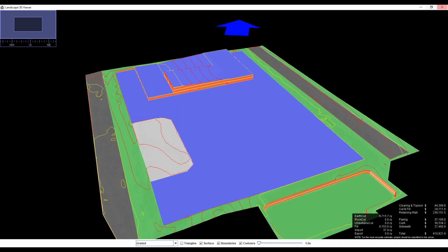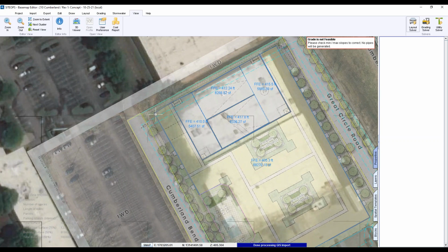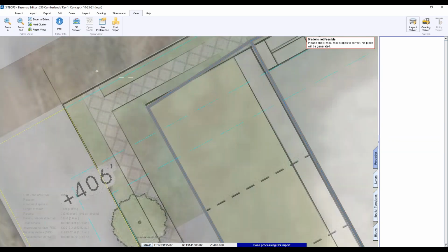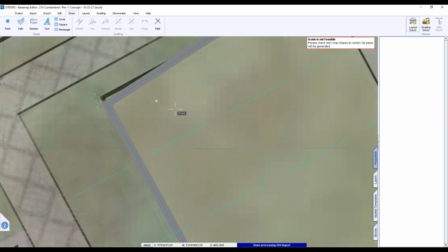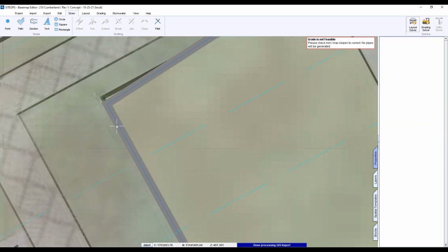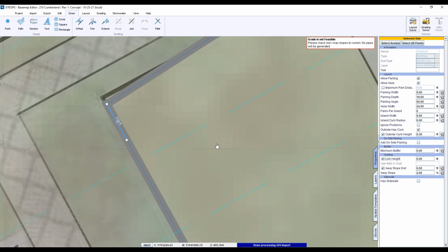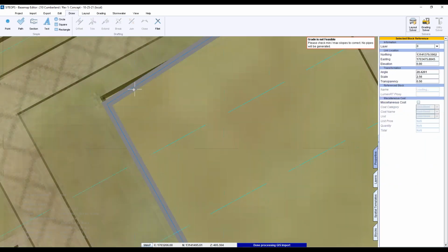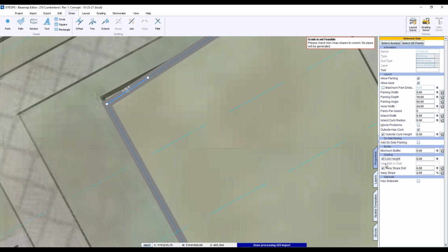So in order to fix that problem, because a lot of this stuff you see in 3 dimensions, what it's doing, and then you're like, okay, that didn't do exactly what I wanted. So what am I going to do to fix the problem? We're at a high point on the site right here, and we want to pin our building up here. So let me throw in 2 points to create these 2 little segments, and then let me link those heights so that it doesn't let it fall below that grade.